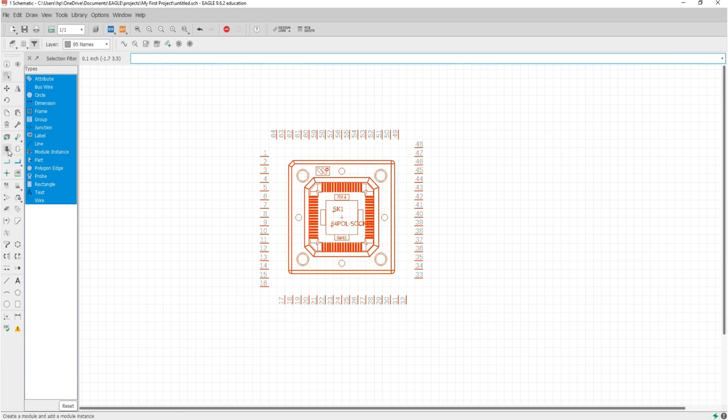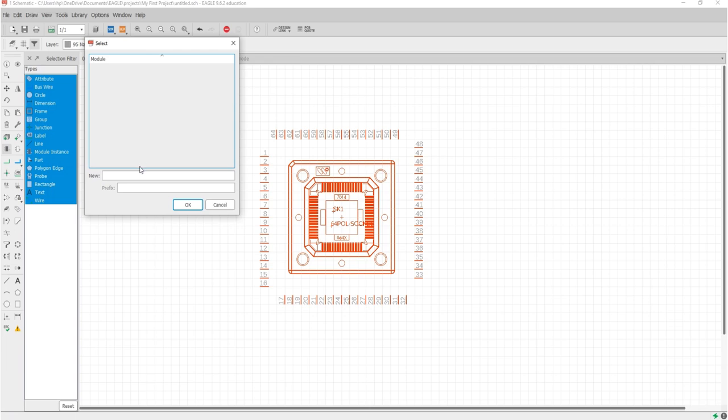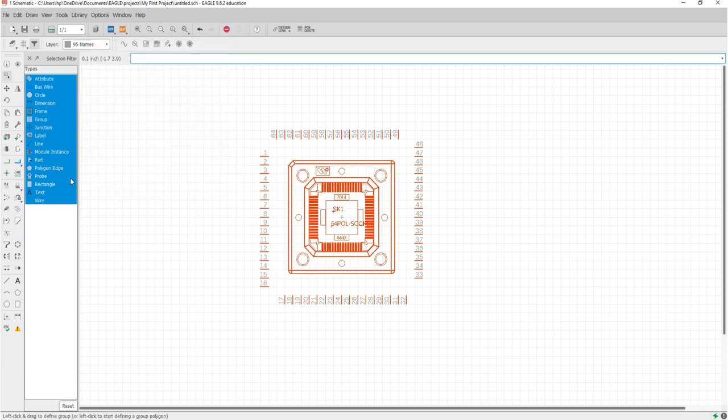Then, the module command defines modules. A module can contain parts and nets as a part of the whole schematic. The module command also inserts module instances in the hierarchical schematic. A module instance is drawn as a simple symbol and represents the usage of a module.